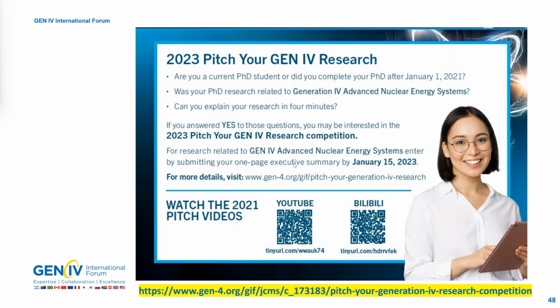Do you carry insurance that would allow you to repair a home if it's damaged? One of the things that we've just recently built into the house hazard system are mitigation strategies. We try to give people a list of bullet points of things they can do to mitigate the risks of different kinds of natural hazards. For example, with earthquakes, it's making sure that your house is anchored to its foundation, really bolted down onto it. That's not always the case. Earthquakes can tip a house off of its foundation, and usually that causes catastrophic damage to the home, and it can be a real risk to anybody in the home as well. So that's a simple thing people can do, particularly during construction, but we also point them to information, usually out of FEMA or the US Geological Survey, that gives them additional resources on how to deal with seismically active regions or regions that are prone to fire.